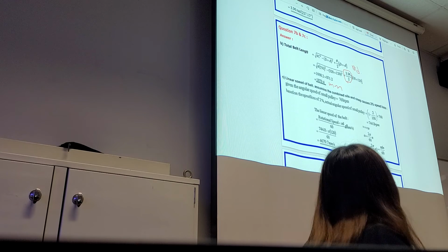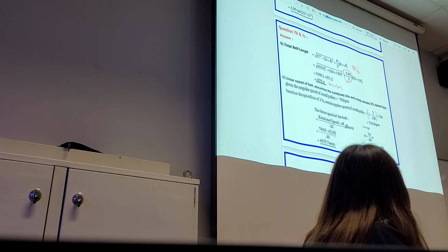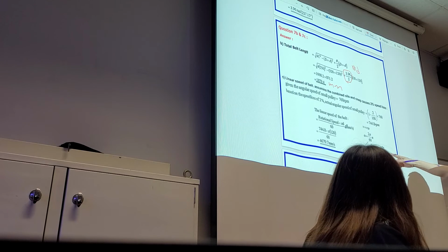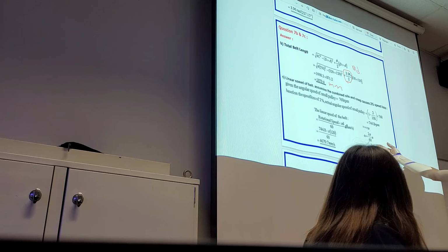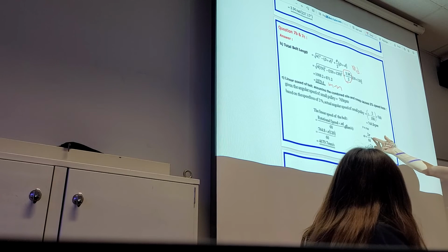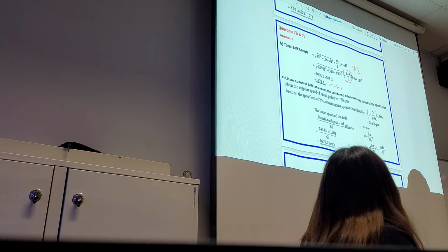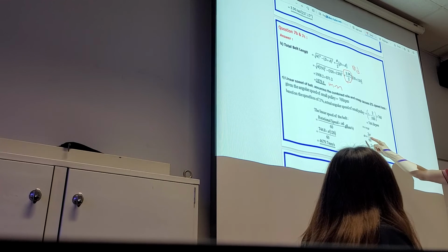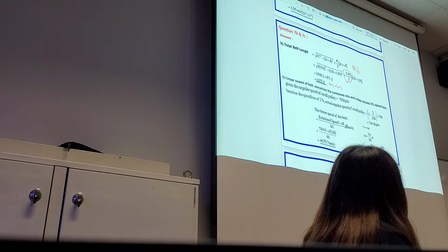The final part is about speed of a belt. The belt will be traveling at a speed. Okay, so what you need to do is using this formula now. This is secondary physics. Okay, omega, angular velocity, times the radius. Omega is basically 2 pi n divided by 60. N is revolutions per minute. So revolutions per minute divided by 60 is revolutions per second. One revolution is 2 pi. So it's a very simple formula now. One revolution, 2 pi, 360 degrees.